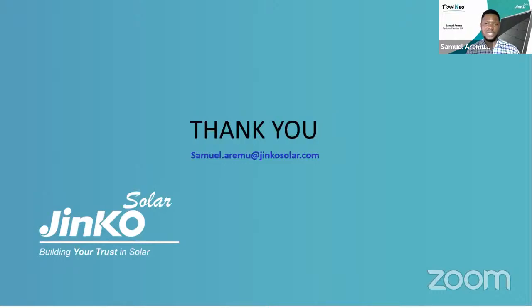And also, I recommend that for small systems, let's say below 1 megawatt, you can go for a DC coupled solution. They're very efficient because you have fewer conversion processes compared to an AC coupled solution. And when you talk about expansion, it's very easy to expand an AC coupled solution because you're just expanding on the energy production side. So these are the basic differences between AC coupled and DC coupled solutions.